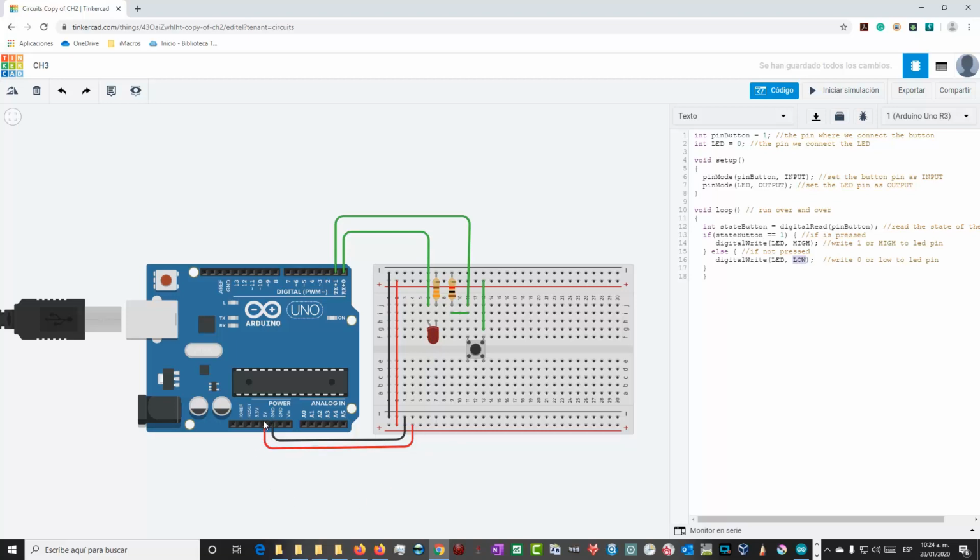You see, I have these pins with 5 volts because this card has all the electronics needed to provide this power. So with all these elements I have a connection here, and now this pin can be used to power my electronic devices. So I use this pin to provide power to the plus line. You see, all these green holes are electronically connected.